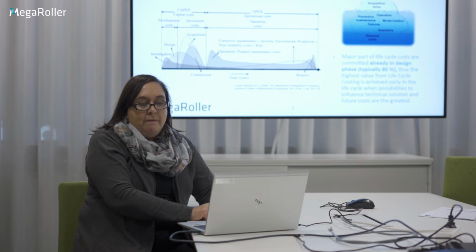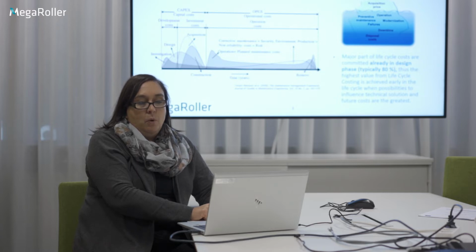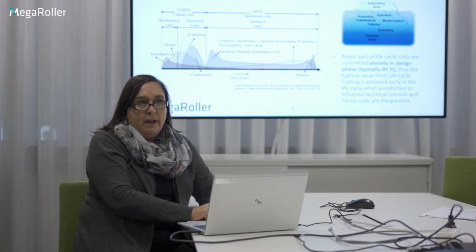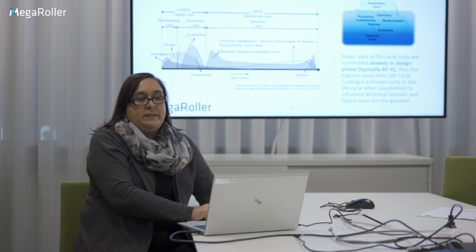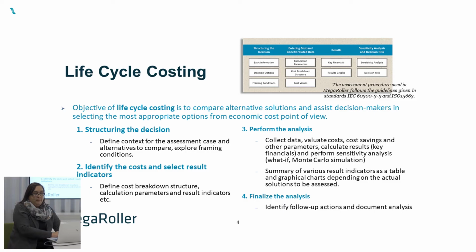And what is also evident is that the major part of the life cycle costs is committed already in the design phase. That could typically be already 80%. So it's very important to do the life cycle cost analysis already in the design phase. And that is exactly what we were doing in the Megaroller project.